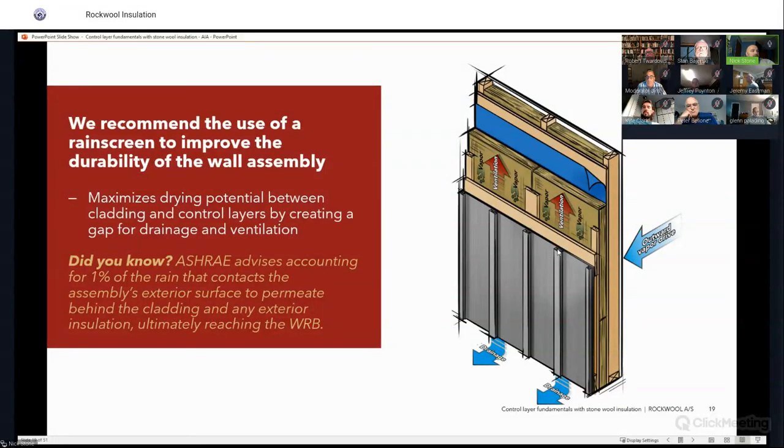So if we didn't have this rain screen on here and the siding was directly up against our sheathing, and that outward drying happened, it would condense on the back side here. Then the sun comes up, heats those vapor molecules, and creates a pressure behind that, pushing on your paint. So that's going to go a long way toward keeping your paint bonded much better, because it gives that